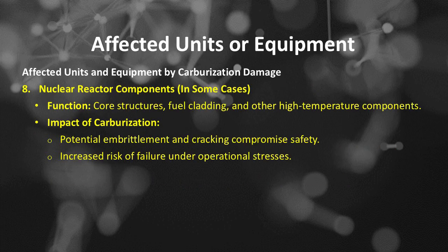Number 8 is nuclear reactor components. In some cases, function: core structures, fuel cladding, and other high-temperature components. Impact of carburization: potential embrittlement and cracking compromise safety, with increased risk of failure under operational stresses.